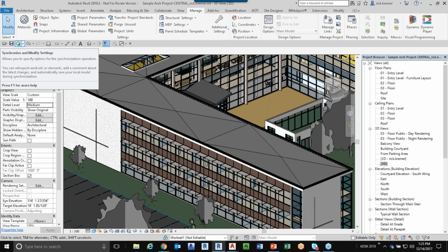I'm going to create a work set on my own and activate that work set and call it mechanical, and then bring in their detached file into my work set of mechanical, so as not to confuse it or make it overly complex. I'm dumping their work sets. You want to keep work sets if it's something that you're going to continue to work on that project with someone else.